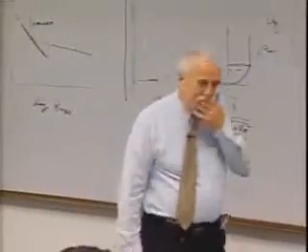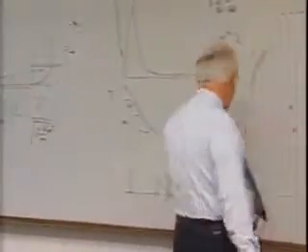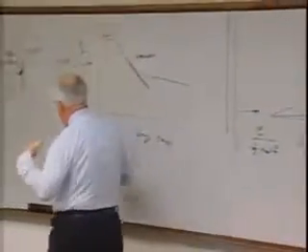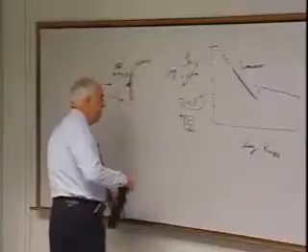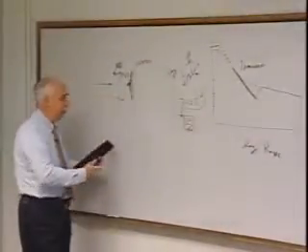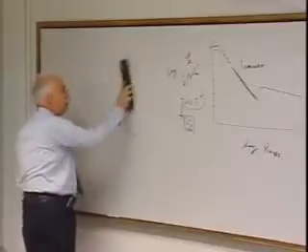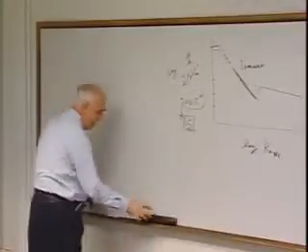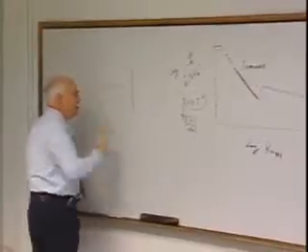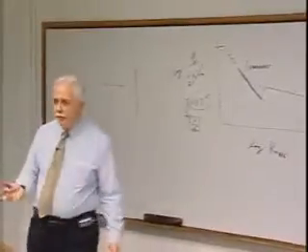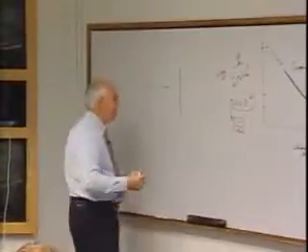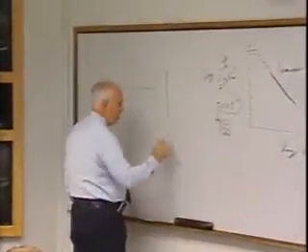Okay, configuration. Everybody's got their own requirements for configurations. From a heating standpoint, I want to put all that energy into the air. So I want a maximum drag configuration. I just want a flat plate normal to the flow. Well, that's wonderful. It's high drag, but it's not stable at all. Okay, so let's go to a sphere.